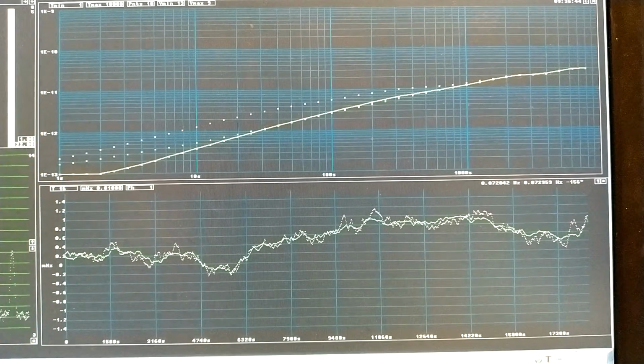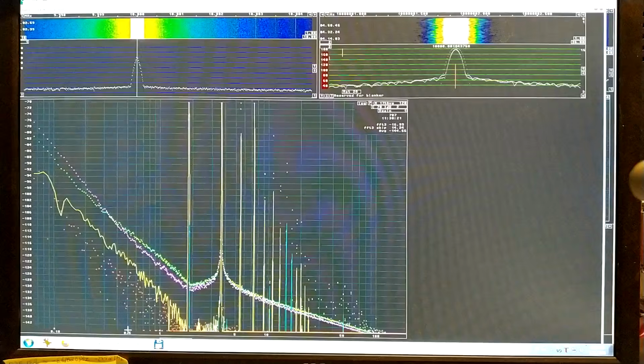So, the bad performance I have seen in this oscillator before was temperature-driven air turbulence inside the box. Having a big box, like the one I am using, creates problems. The temperature has to be even inside it. This was unknown, and I have probably had the same problem earlier in other oscillator designs.